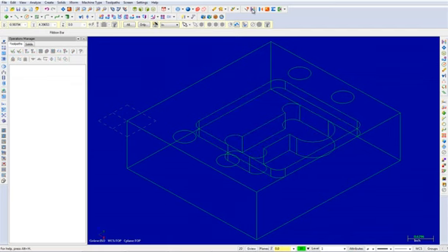When performing a transform function, Mastercam creates a temporary group from the originals, red, and a result, purple, from the transformed entities. These system groups appear in the Groups dialog box. However, they stay in effect only until you use the Screen Clear Colors function or perform another transform function.